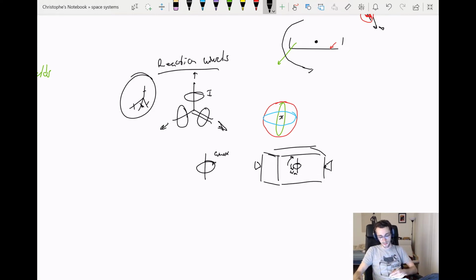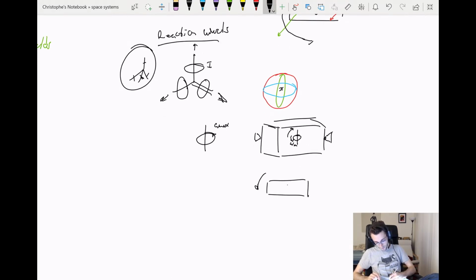And what that does is, looking from the top now, we're still at our same velocity. So let's start from the beginning. This is our reaction wheel, it's at omega max, and we'd be spinning the other direction at our omega max, omega satellite max. And we use our thrusters, so say we've got our thrusters here and here, to speed up along that axis.